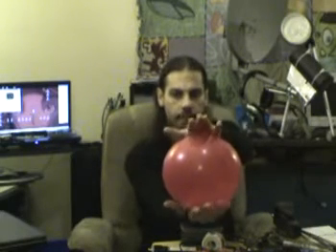What your antenna is basically doing is it's going to manipulate this field of energy so you either have more or less gain. So, right now we have a perfect sphere. Now in radio this will never happen, this is just for visual sake here. Now, we have an antenna, and let's say today we're going to make some dipoles. And what it's going to do is, it's going to take this ball of energy, this estimated radiated pattern, and it's going to squeeze it. And if you notice, when you squeeze it, the sides squeeze out.